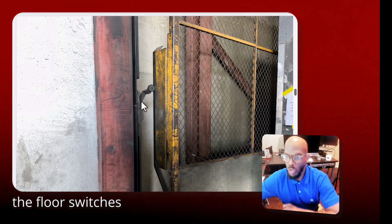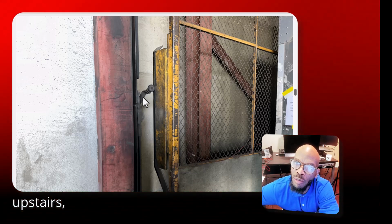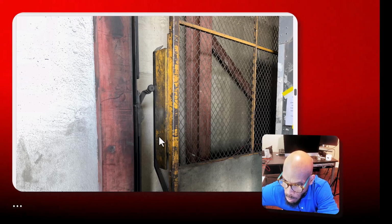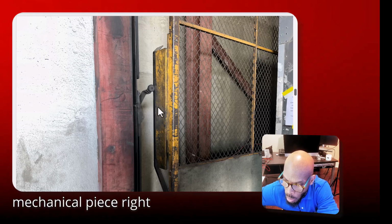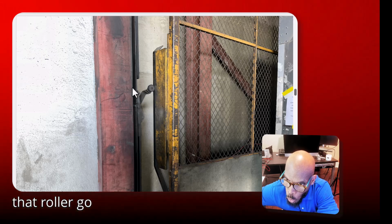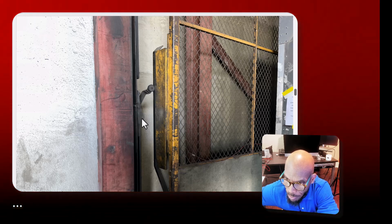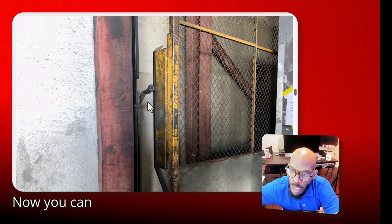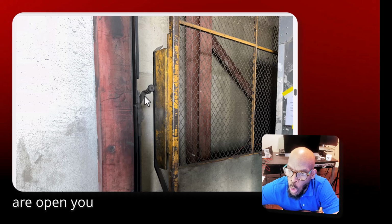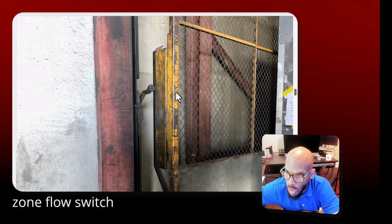Here we have the floor switches that I keep talking about. This is a zone switch, and you have one of these upstairs on the 4th floor, and you have one downstairs. You see this mechanical piece right here, it comes down and it hits this roller, and it makes that roller go back, and that's how the lift knows what floor it's on. Now you can get to this if you just walk up to the lift. When the doors are open, if you look to the left, you'll be able to see it. This is the zone floor switch.